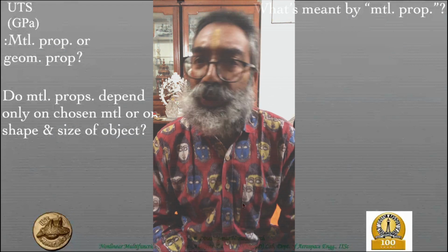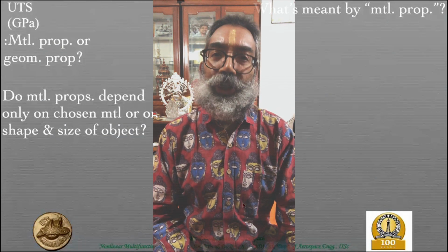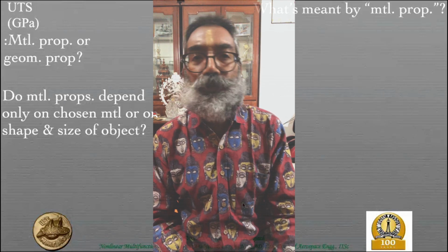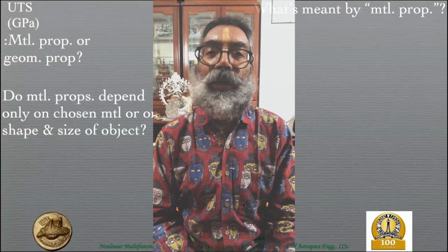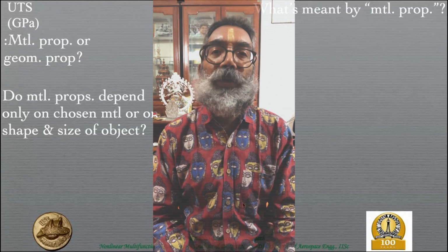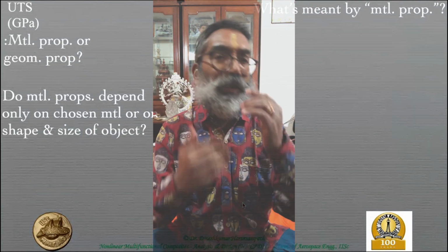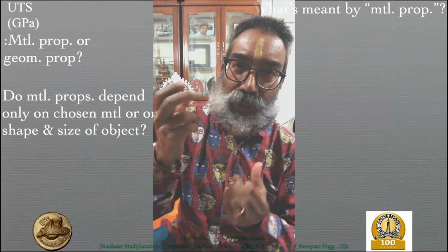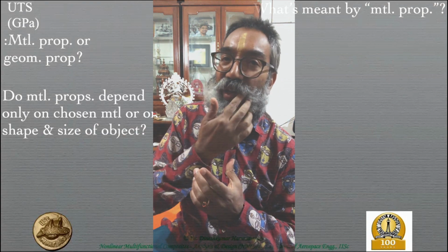How do we determine the UTS? You typically have a uniaxial testing machine, what you call a UTM. Once you get back on campus, those of you who are MTech students will be doing certain experimental testing as well. Some of you might have already seen a UTM in your BTech labs. You create a certain specimen and test it all the way to failure.